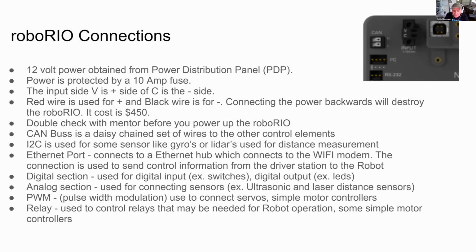It's an industry standard. It's used in your car. And again, we've already talked about I2C. That's controlled right here. And here it happens to have 4 wires. Turns out that this typical standard is a power lead, a ground lead, and a clock lead and a data lead.